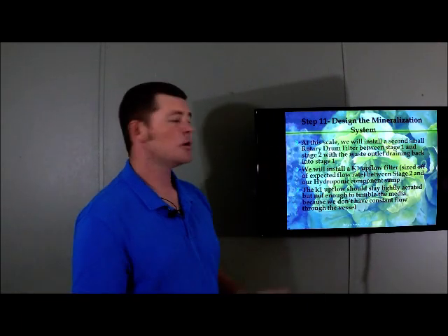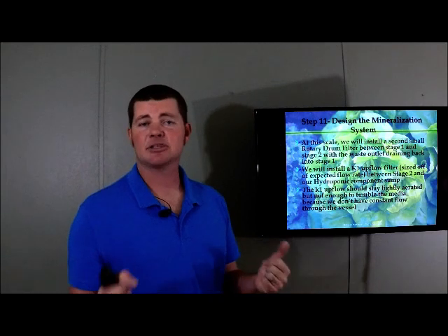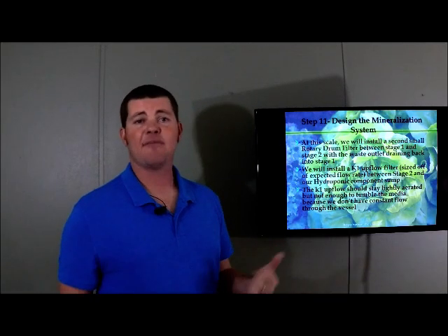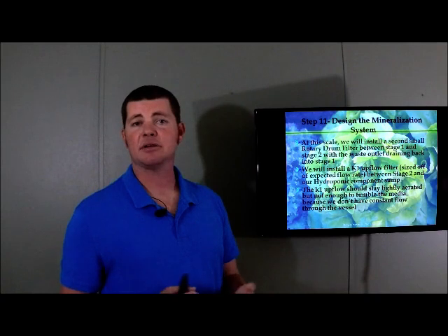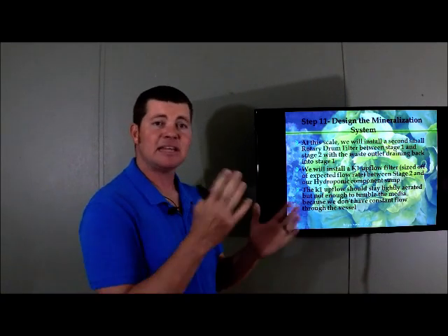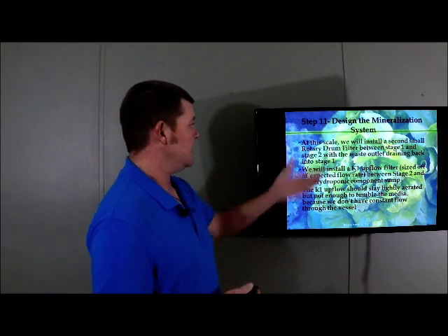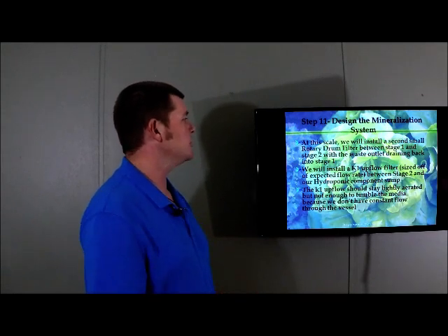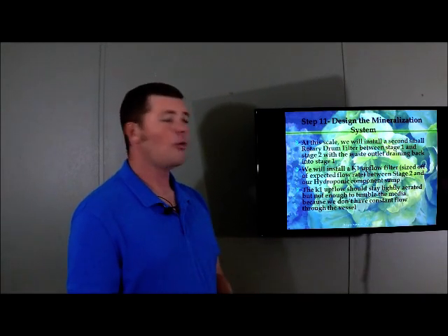If you don't want to use a drum filter, you can make a giant static screen, pump into that, and have a worker pull that and spray it out every day and put it back into the stage 1 M tank. But in this design, we're going to put a rotary drum filter between those 2 stages. And again, all the waste collected goes right back into stage 1.